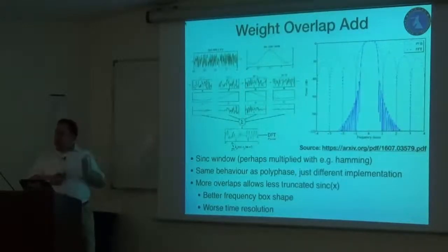And that might be hard to believe at first, but actually that is the same as doing an FFT with a higher resolution and this window function, and then adding 4 bins together. That would be computationally very expensive, but thanks to this polyphase transform, you can put this at the front of the FFT and use a smaller FFT.